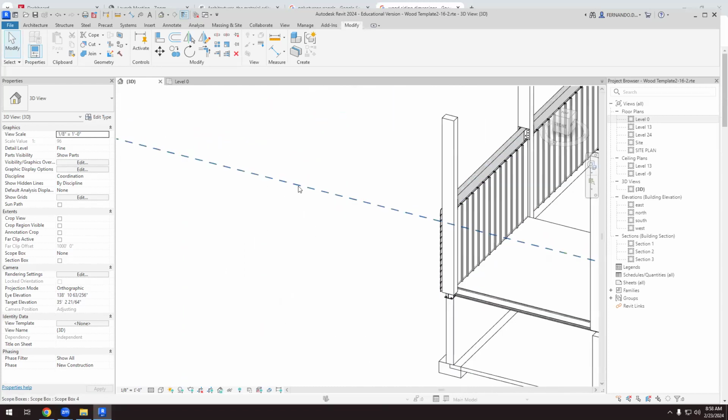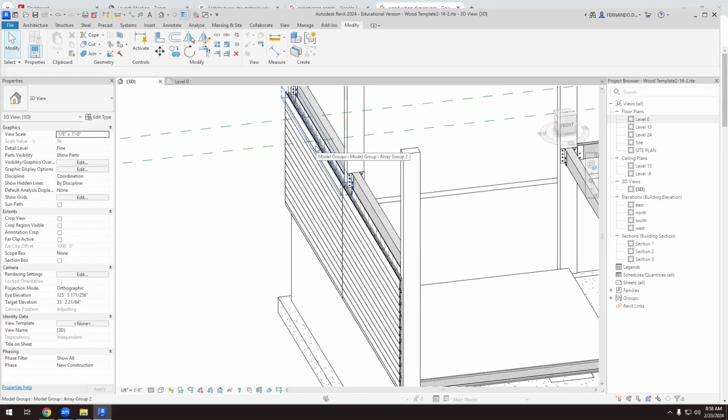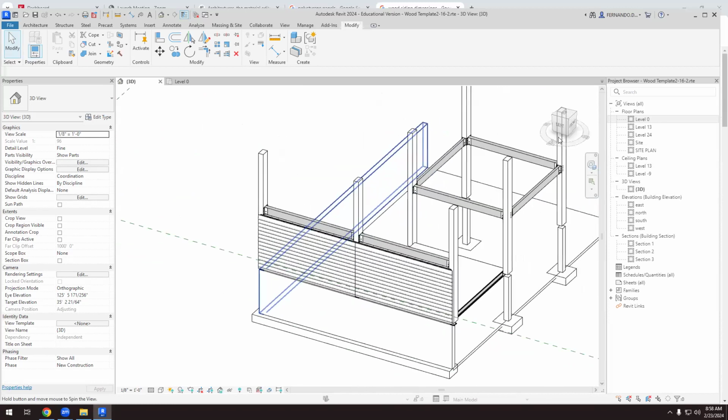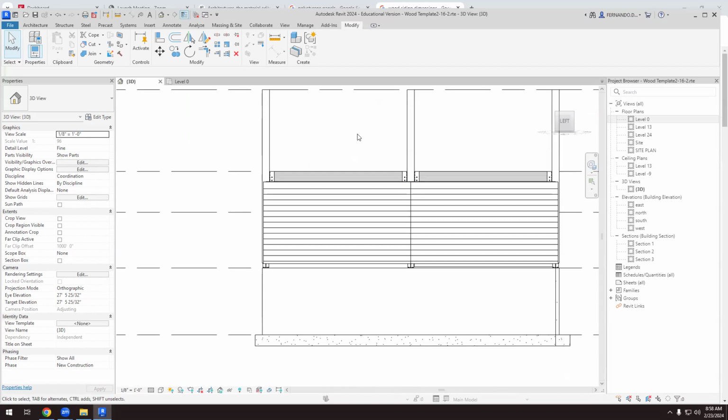Well, I have a lot of solid elements here, so I can make the most of all these vertical and horizontal studs that I have created. And then I will open a window following those vertical and horizontal elements. So this is the first decision that we have to make. In Revit, when you have a typical wall, you can select window and place the window wherever you feel like. In this case, we are creating all the structural elements, so we can't place the window anywhere. We have to realize where the structural elements are.